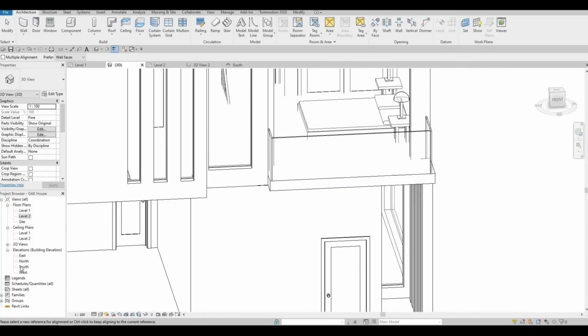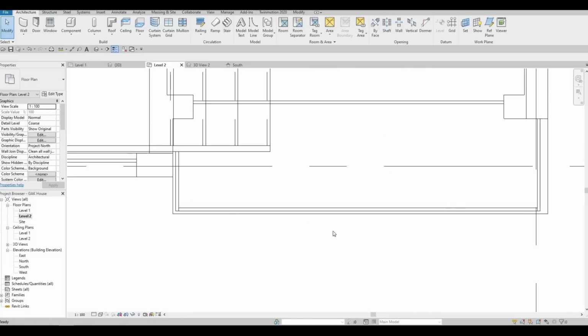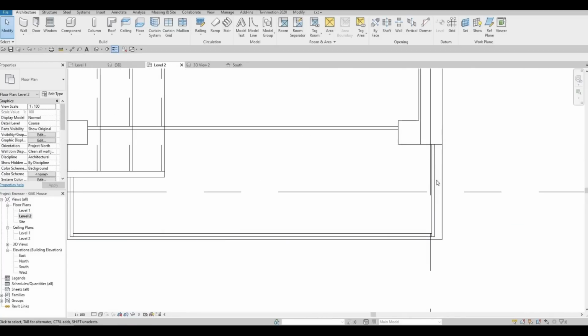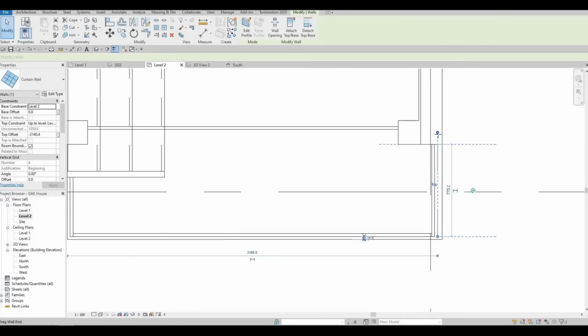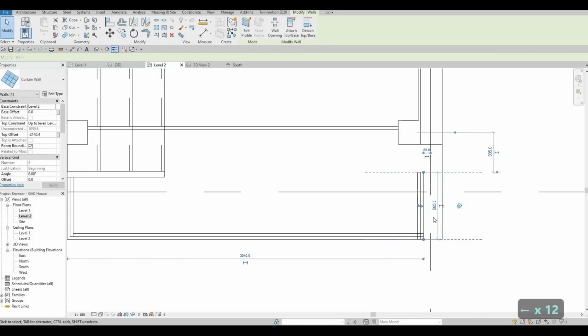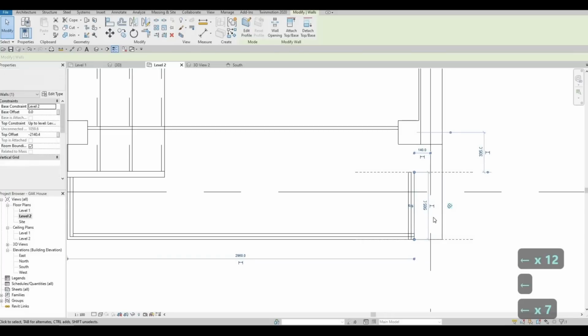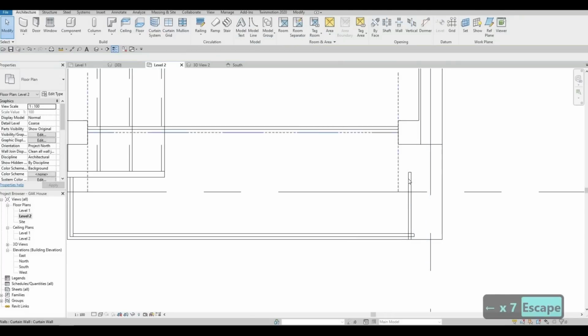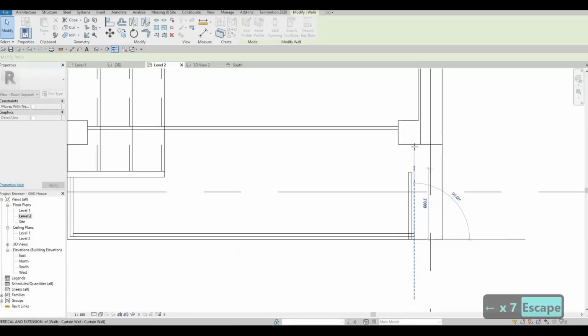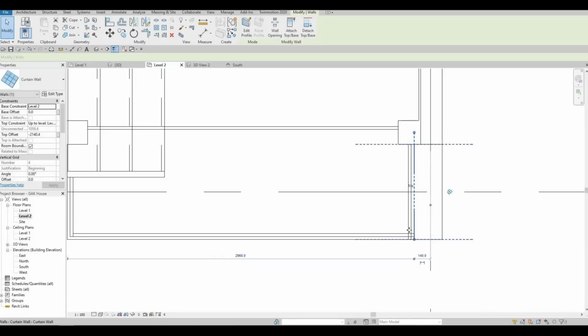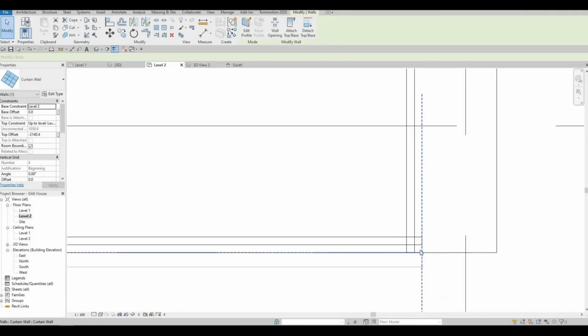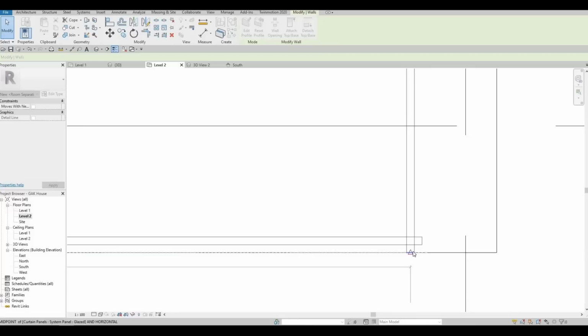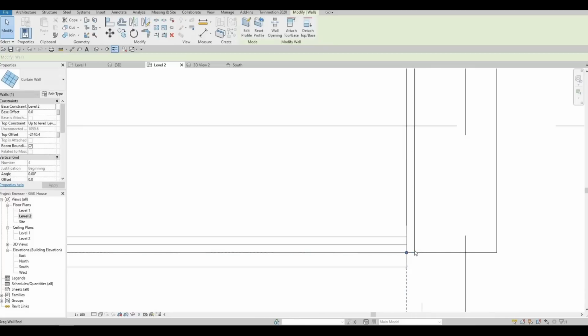I want this one to be moved because I'm gonna add in an extrusion right here. So you will need to drag it all the way there. It's because like earlier when I did it, it moved the whole thing. It's because you consider this as a wall, and when you move a wall, it will move everything.